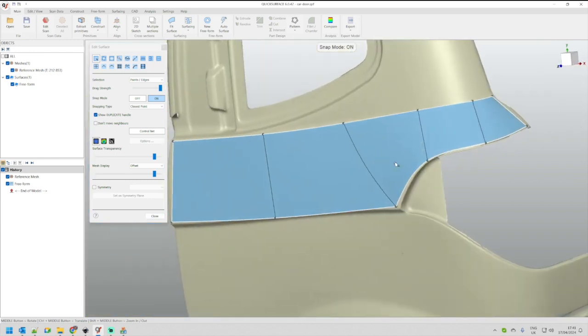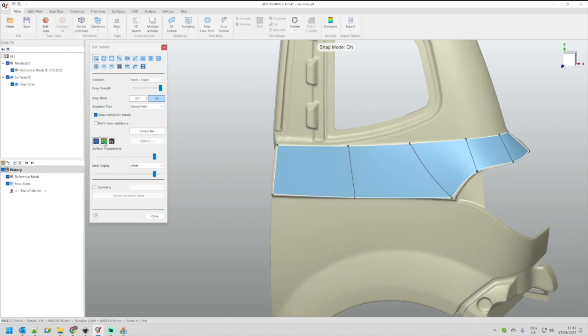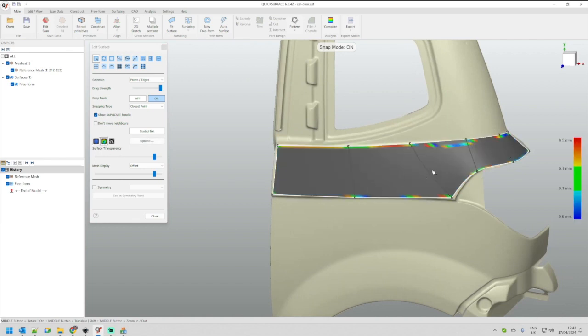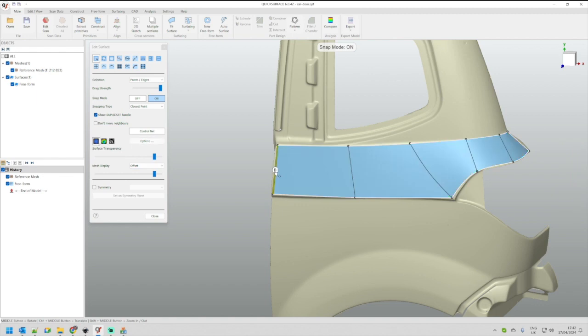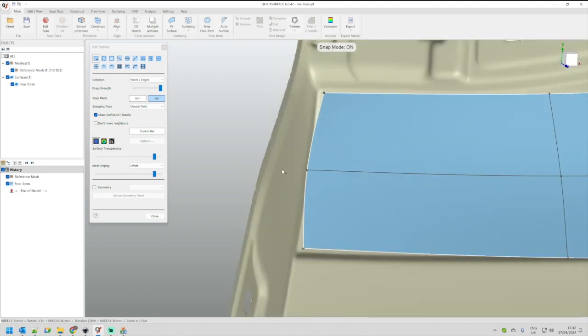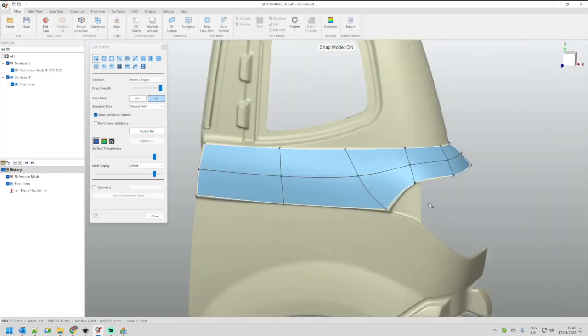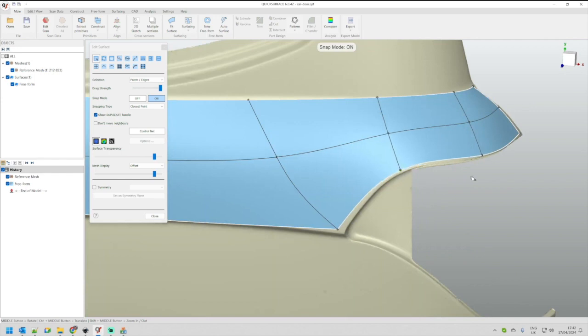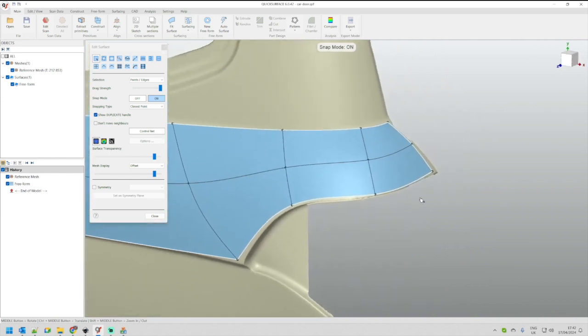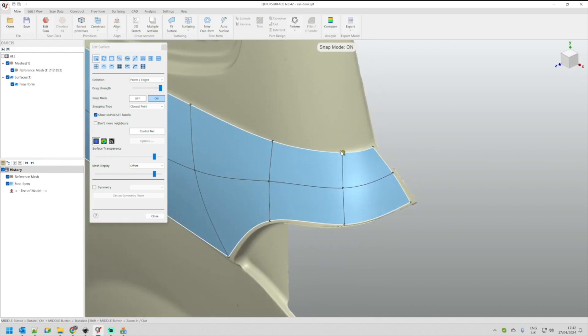For the purposes of accuracy here, if I just evaluate, this is really off from my scan data. I can use tools like, for example, select this edge, press the S command to split. You can see that it's automatically created this. You can find very detailed tutorials on how to use our freeform tools. Don't hesitate to explore. This is not the main goal of this demonstration.